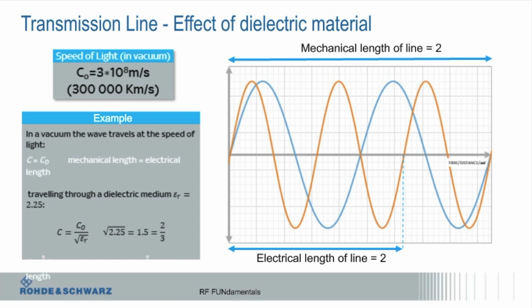So you're getting reflections from each of those connections. So A, use really good connectors if you care about this, and B, minimize the number of connections, right? If you have an SMA and you need to get to an N, get the right adapter. Ideally get a cable that has the right connector for that interface. That's really more the moral of the story.